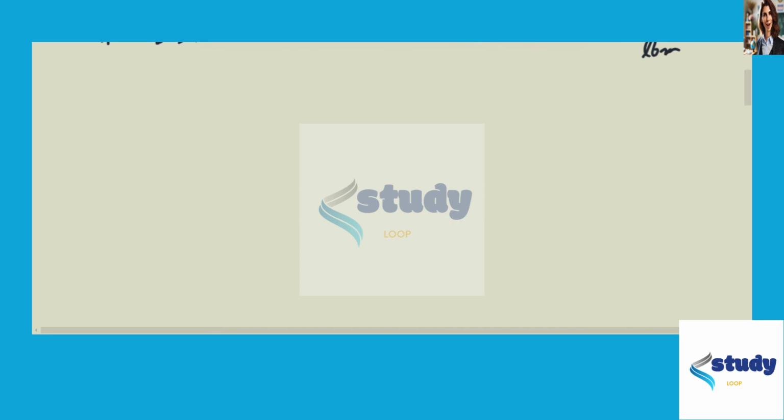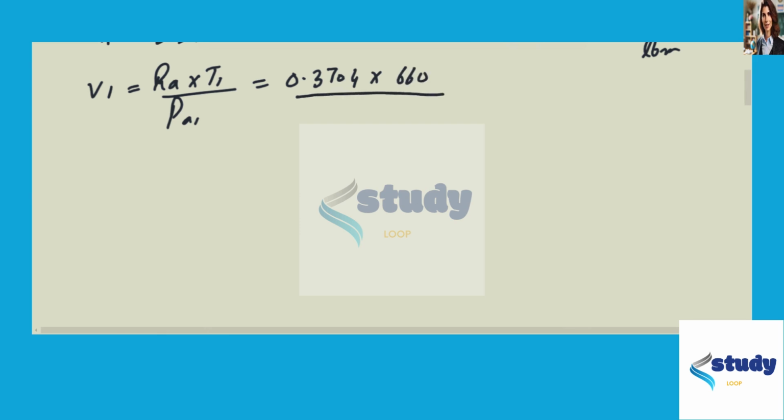So guys, moving further, we've got v1 equal to RA into T1 divided by PA1, and that is equal to 0.3704 multiplied by 660 divided by 58.462, and that is equal to 4.182 cubic feet per lbm.